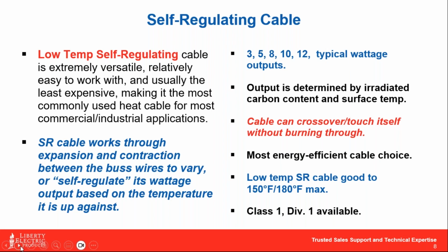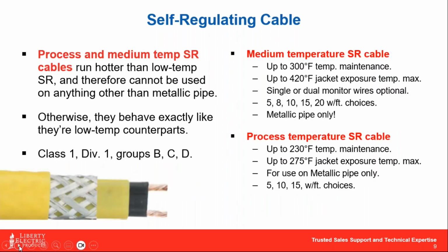Based on those temperatures alone, you can put this together with something like PVC or plastic-based piping, and it becomes a very safe alternative to use with them. Lastly, this is a cable that is rated for Class 1, Div 1 and Div 2 applications. It's a fully sealed unit, so the terminations and fittings we would put with it would make this compliant with any Class 1, Div 1, Div 2 application.